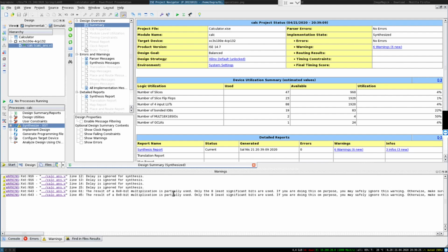When you do an 8x8 multiplication, 8-bit by 8-bit multiplication, what do you get? You should get a 16-bit result. But we are unable to display 16-bit results in our 8-bit LED display. So what we do is that we only look at the 8 least significant bits.